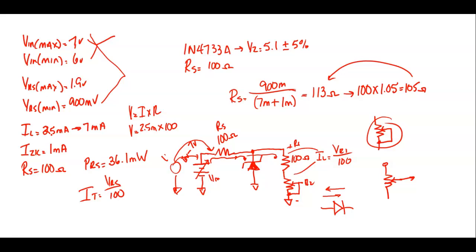What we're trying to do is set our load current. We're trying to set our load current at 100 milliamps. I'm sorry, 2.5 milliamps. Okay. But I'm measuring the voltage across a resistor. So I'm trying to figure out how much voltage the 100 ohm resistor would drop to conduct 2.5 milliamps. Everybody understand that? So how do I calculate volts if I know current and I know the size of the resistor? What's the formula? Not for voltage. That's power.